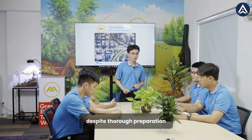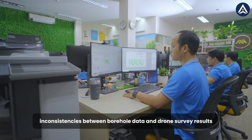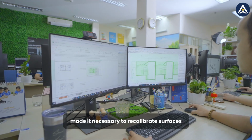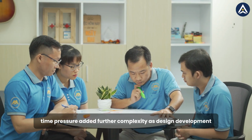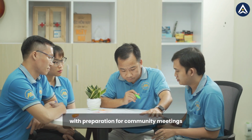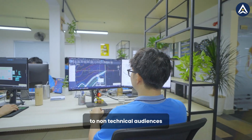Despite thorough preparation, the project faced several challenges. The site's complex terrain and geology required multiple surface models and continuous data verification. Inconsistencies between borehole data and drone survey results made it necessary to recalibrate surfaces and recalculate cut-and-fill volumes to ensure accuracy. Time pressure added further complexity, as design development, data updates, and technical verification had to progress in parallel with preparation for community meetings.